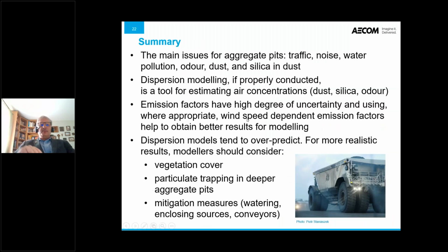And I should conclude with a summary. The main issues for aggregate pits are traffic, noise, water pollution, odor, dust, and silica dust. Dispersion modeling, if properly conducted, is a good tool for estimating air concentrations. Especially when the pit is not already built, you could predict what concentrations could be in the worst cases when it is operational.